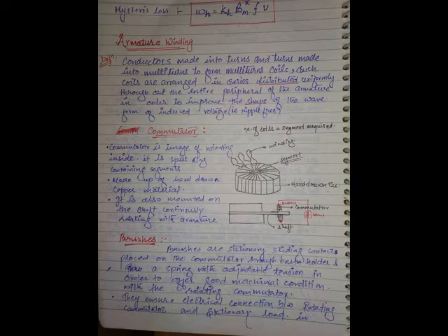So in this entire armature, you require 2 points to collect current. Any point. Which is the best condition, best axis to collect current from the armature? Is it MNA or not? Neutral zone. In order to achieve the collection of current without any sparking in a DC machine, always brushes need to be placed on MNA.